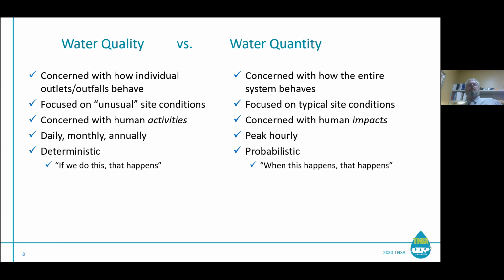And then in water quality, we're talking about TMDLs. We're looking at long-term continuous loading. Whereas in water quantity, you want the worst hour of a 10-year period. You want to know that system completely under stress, because otherwise your system's probably designed to take the first inch, whatever else, the stuff it's going to see regularly is really of not much concern to water quantity.